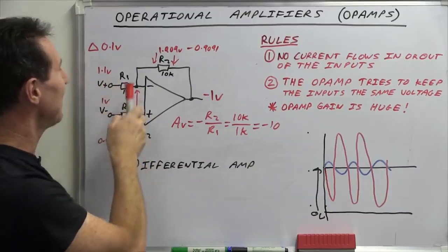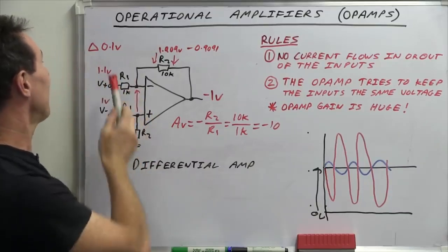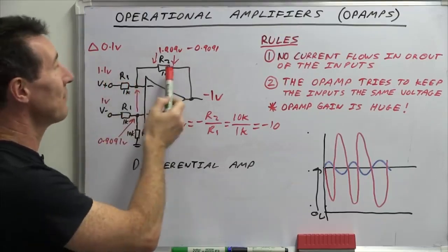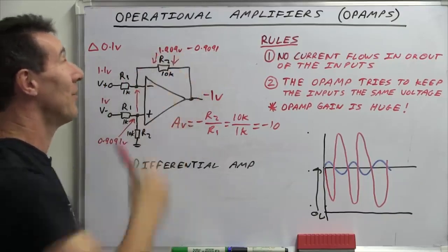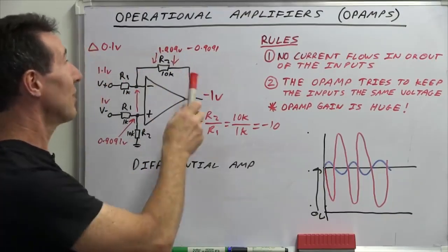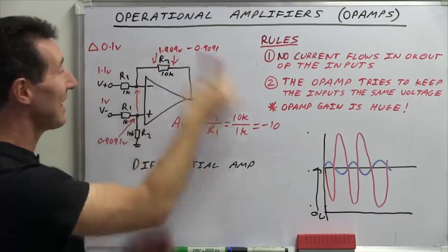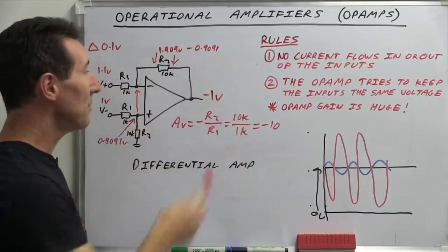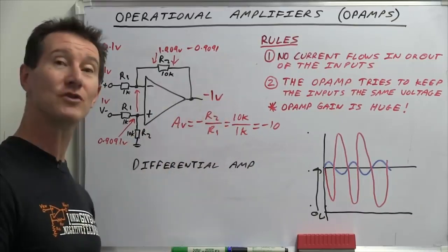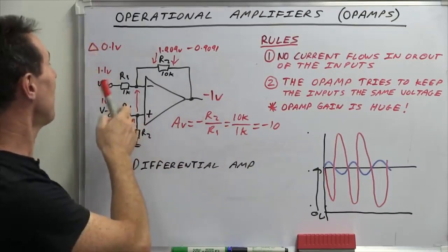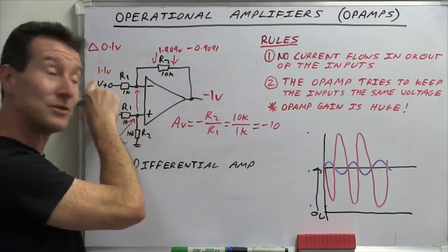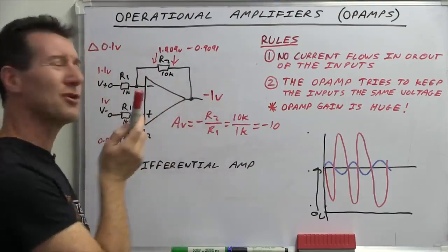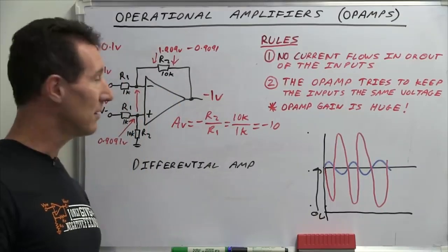That has X, and then you subtract that from that, you get X amount of current flowing through here, which then must flow through the 10K, which has 1.909 volts across it. Subtract the difference there. It's exactly the same configuration as before with the bias voltage, but then we're left with an output voltage of minus 1. So we've amplified the difference in our input signal by the gain here, 10. It's not a terrific differential amplifier, but it works.